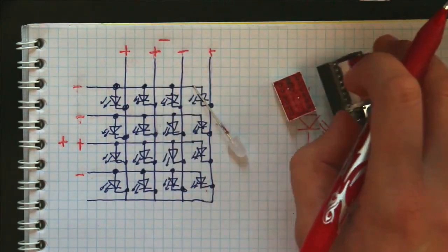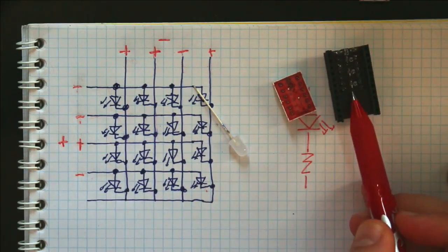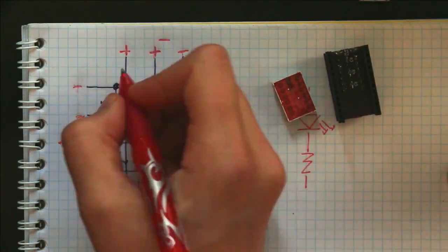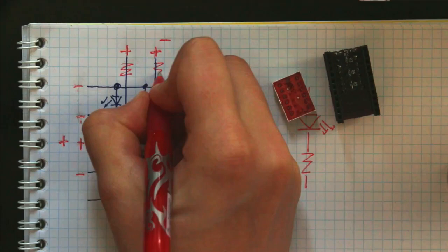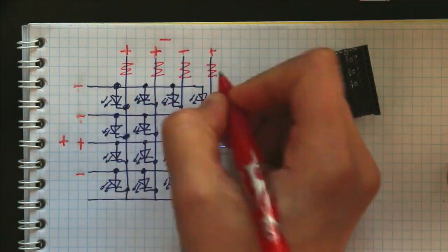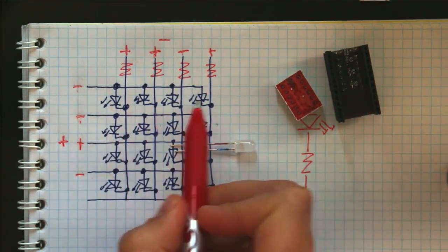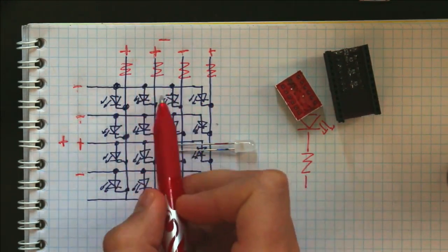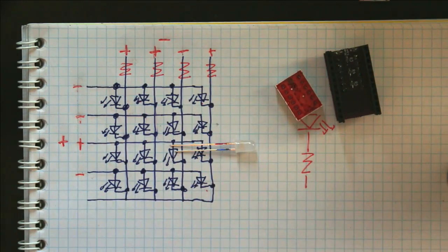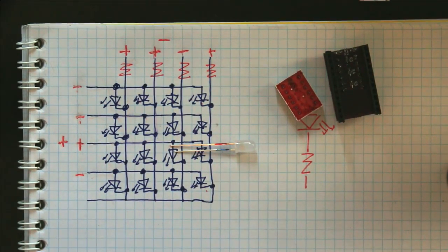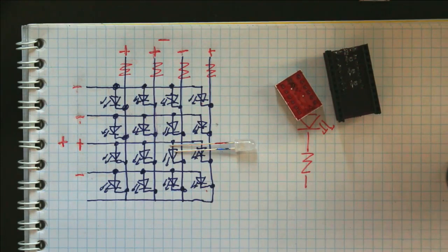So that's why in this LED matrix display, I have the 5 resistors on the back. So that could be represented like this. And that allows each one of these LEDs to operate at the correct voltage with the correct current. So I hope that explains why this whole thing works the way it does and a little bit of how you would program it in your microcontroller.